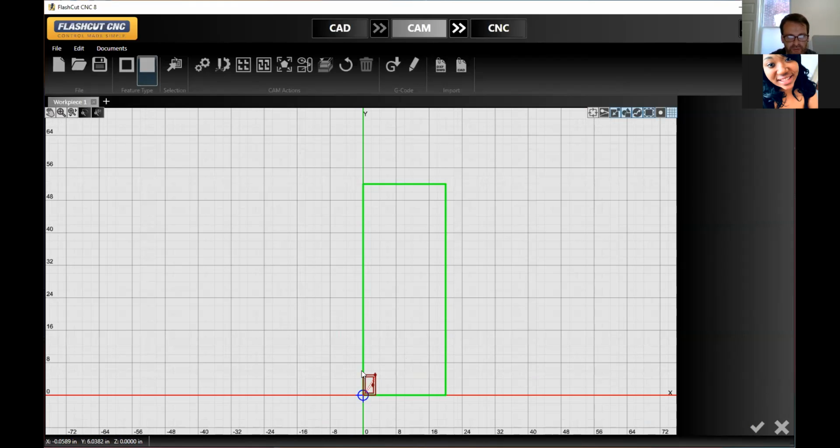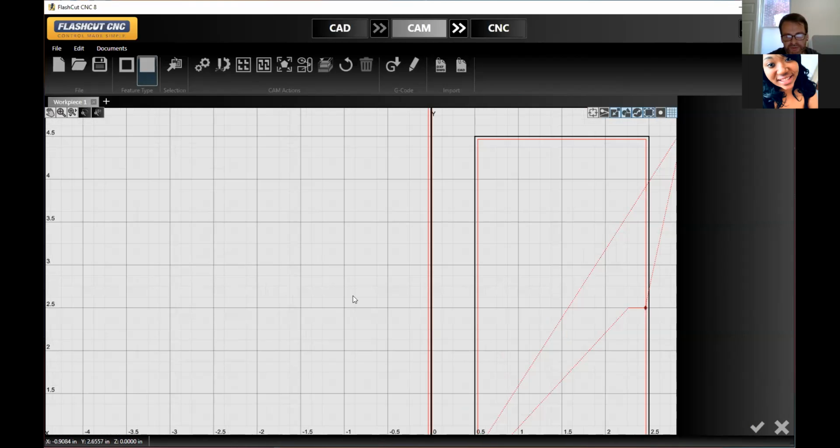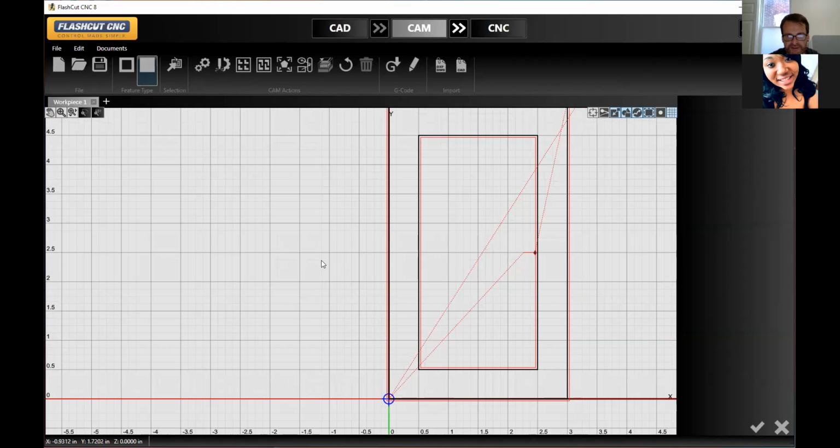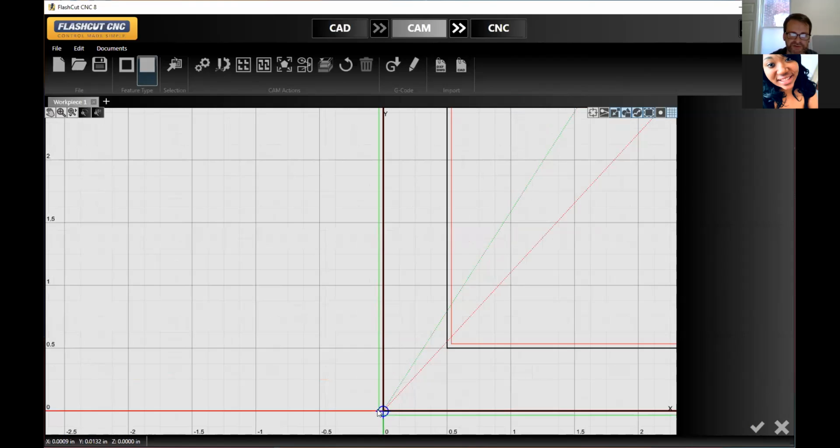We're going to get an error message because when the computer generates lines to cut things, it always generates like 2 to 3 lines to make the cuts. And the computer's cut path travels outside of 0 by 0.034 inches.